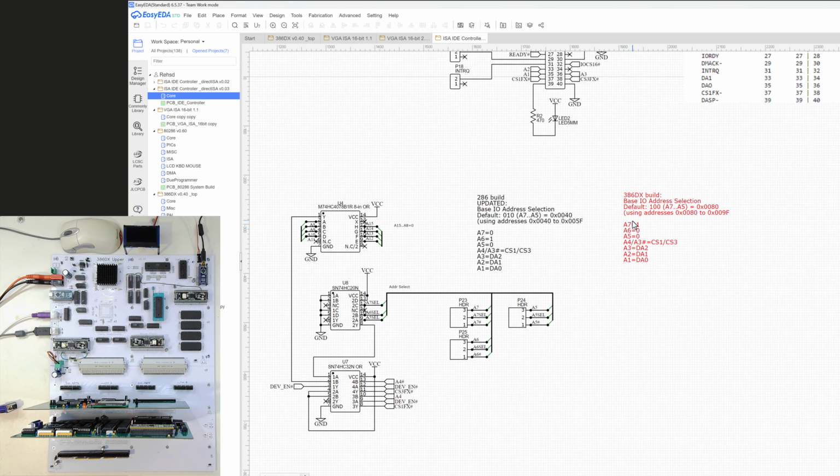So shift all this stuff up a bit on the address line, and then leave A1 and A0 open so that the processor stays on the double byte boundary. So I'm not using the bottom two address lines of A1 and A0 for my decode or for my transfers. All transfers should happen on a double byte boundary. So A1 and A0 should always be 0.